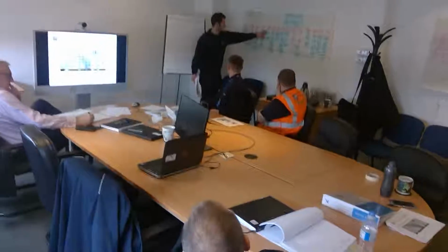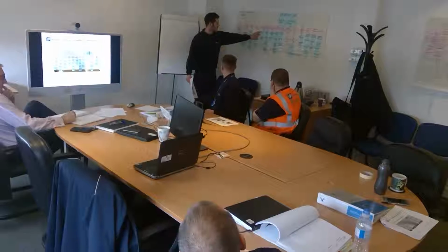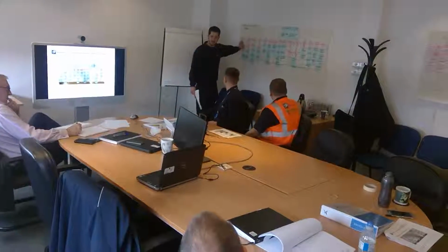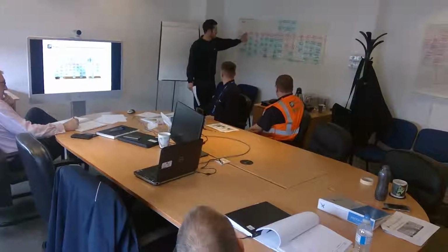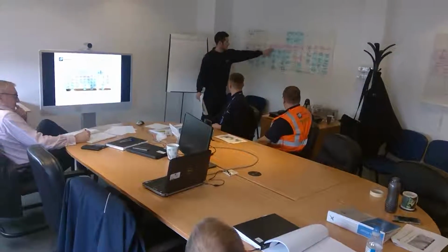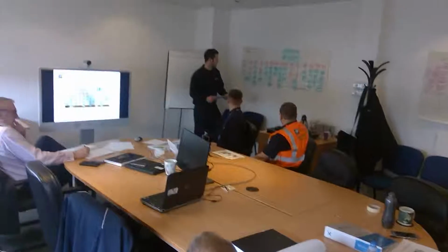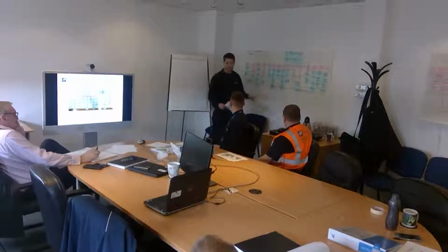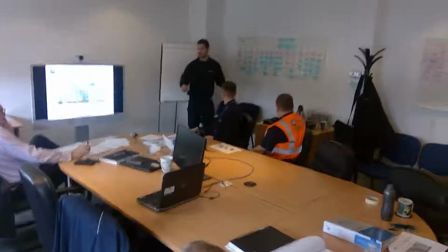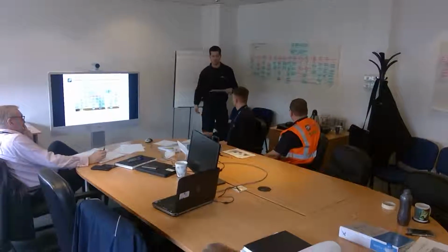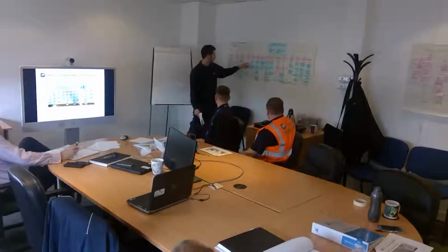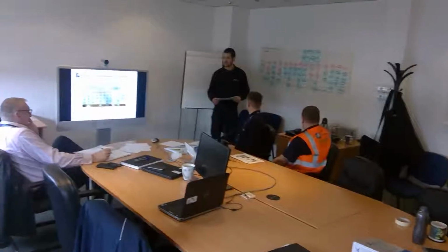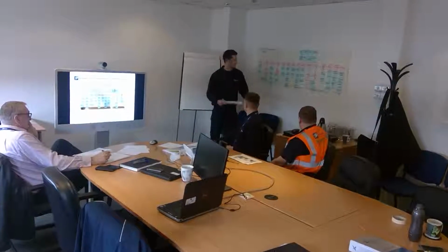So we move on to creating a cutting list. Problems that can arise with that are human error, and unachievable dimensions that haven't been picked up earlier on in the handover process or joint checks. From that we start cutting, so it's actual cutting and prepping of the pipe ready for the welder. We can have measurements and marking wrong, so just a human error with a tape measure, measuring a metre when you're actually measuring 2 metres or whatever it may be. Tooling issues, the saw might have gone down, we haven't got any blades, blades are wrong, blades are blunt, anything like that.